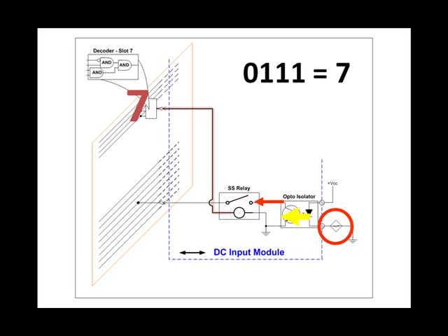This diagram is slightly different than the previous one because it represents the relationship between the backplane and a single output. The previous diagram was for an input circuit. This is an output circuit, one of 16. This is an output, and its state was stored in memory by the rung of logic that controls that output. So in this case, we're not sending something to the controller. The controller is sending something to the output.